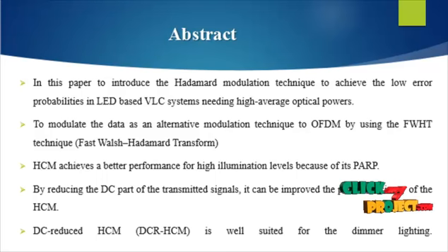Visible light communication refers to the communication technology which utilizes visible light sources as a signal transmitter, the air as the transmission medium, and appropriate photodiodes as the signal receiving component. Visible light is the form of electromagnetic radiation covering wavelengths from 390 nanometers to 750 nanometers, that is in the terahertz range, 400 to 800 terahertz. VLC is a subset of optical wireless communication technologies.